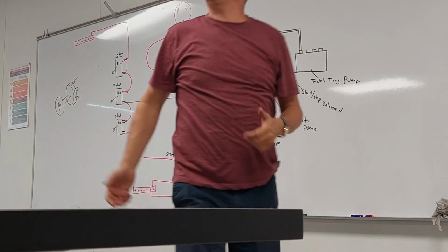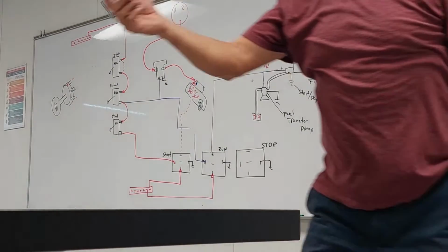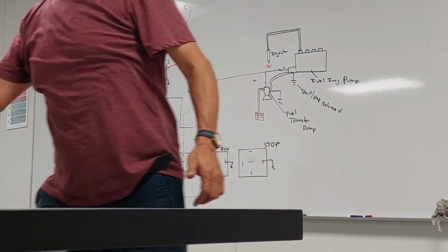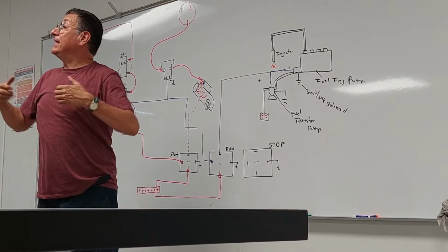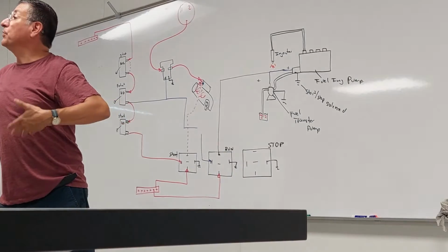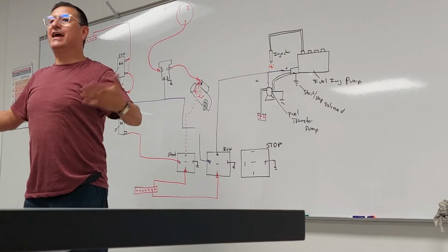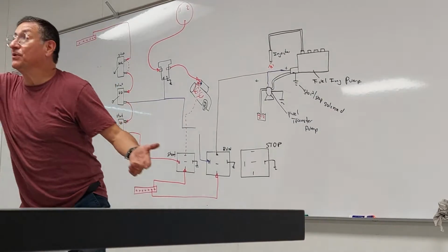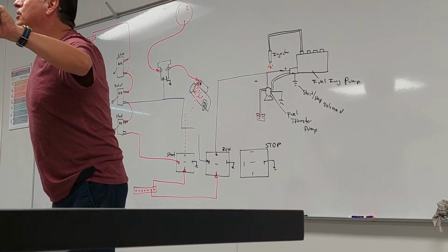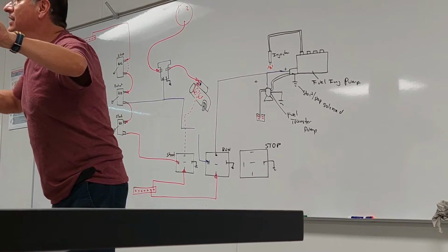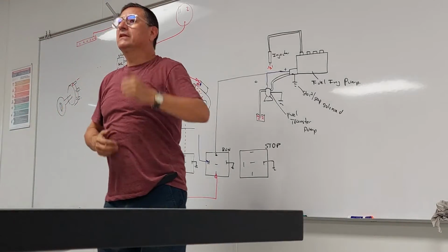How can you solve that issue? Excuse me? The other relay, with power coming from the output of the alternator. When the alternator of the engine produces its own current, you can remove your finger and the engine continues. For that reason, in the majority of engines, you need to hold that button 10 seconds, no? Until the alternator produces power, you remove the finger, and finito, the engine is running.